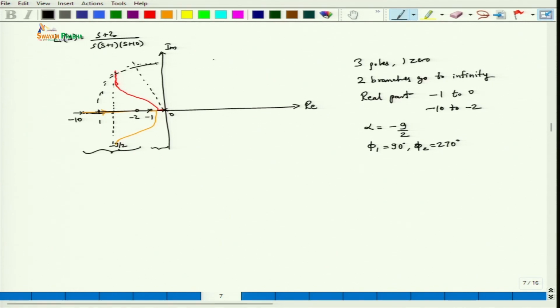So both specifications are met. So basically for a gain equal to 70, we get zeta is equal to 0.56 and omega n is equal to 7.7 radians per second. So this is basically acceptable to us, based on this time domain specifications which we have been given.